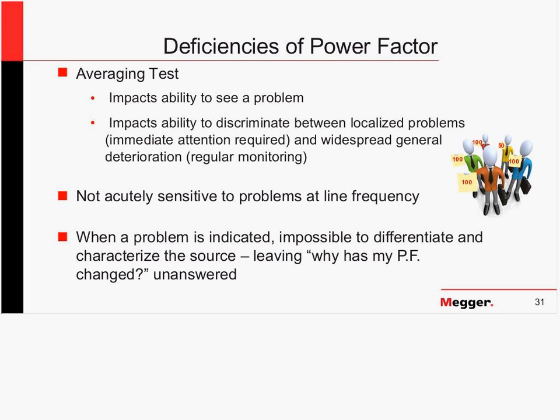So it tells me, gosh, it's not fantastic. I'd like it to be better. So I can see more information when I make a sample size smaller whenever I'm dealing with an averaging index. So power factor is the same way with insulation. It's why there's procedures available to always minimize the size of an insulation system when you're testing. That affords you the opportunity to see better.